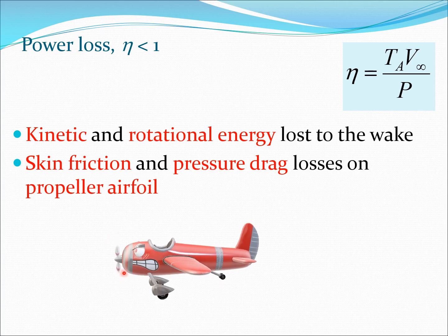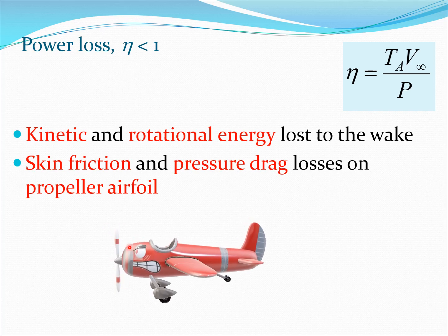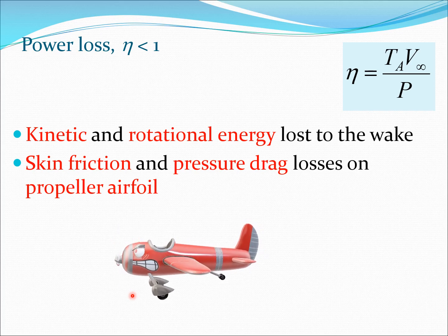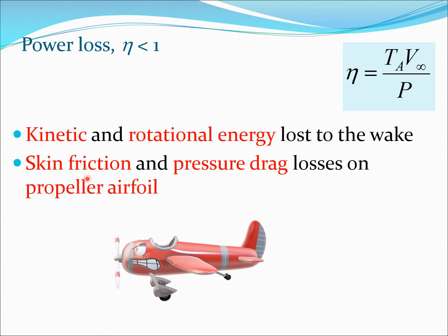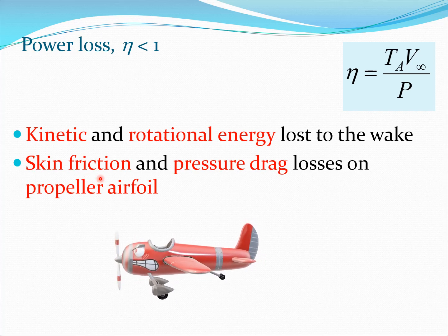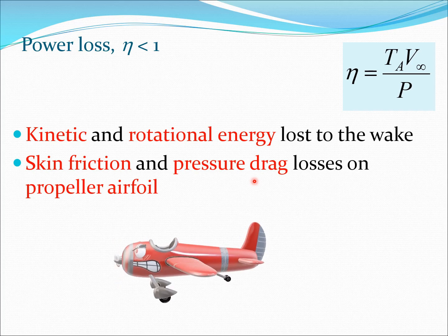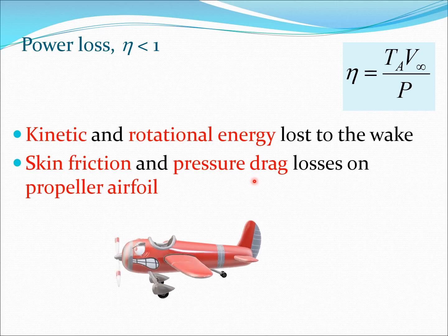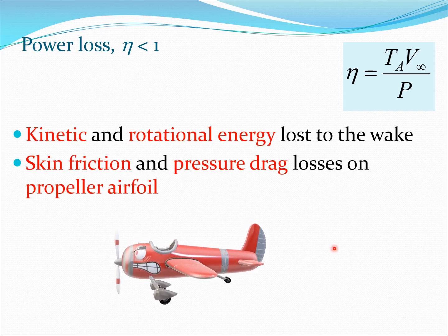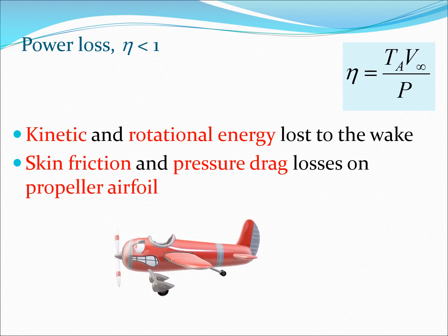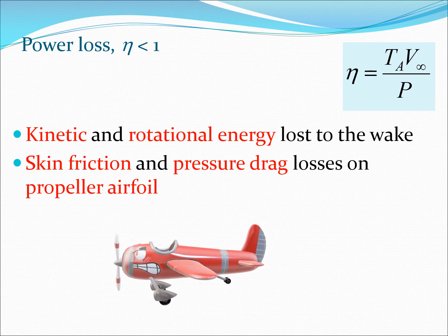Also, there is going to be skin friction and pressure drag associated with the propeller airfoil itself. Remember, in our earlier lectures, we had a lot of discussion about skin friction drag, boundary layer, and so on. And also, we had discussion about pressure drag. Remember the issues related to separation, especially from laminar and turbulent flow. So, all these contribute to drag, and therefore, there is a lot of loss as far as the propeller is concerned. And these are things which do not directly go to create your available thrust.